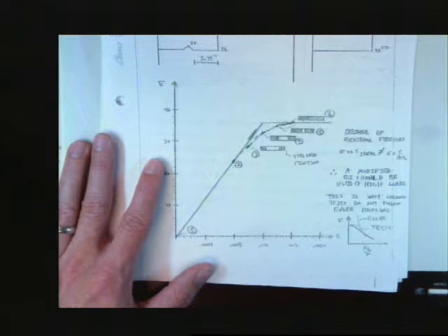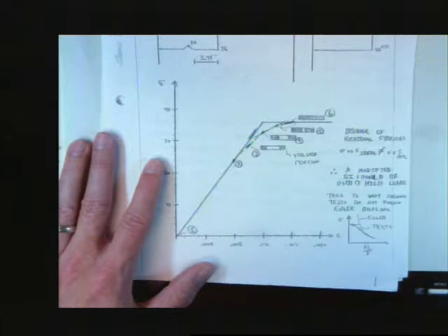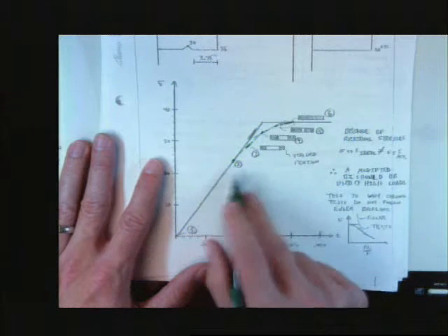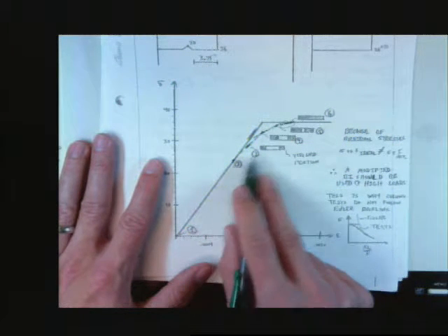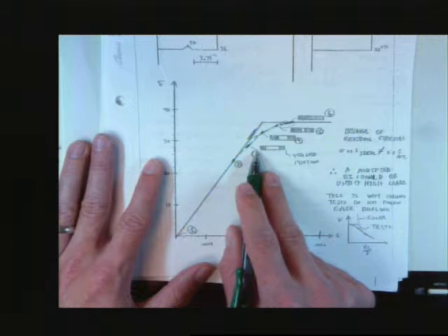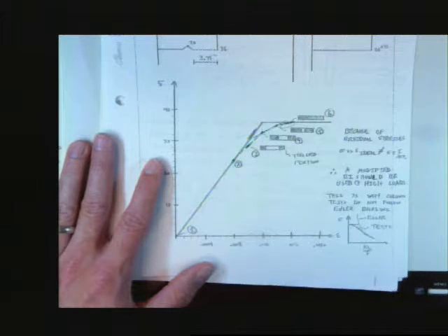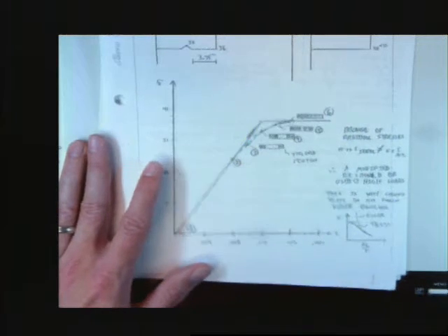That means that initial assumption, that the modulus of the girder and the modulus of the beam or the modulus of all columns are the same, is not right. Because if you get this area above 0.44 Fy, it doesn't apply anymore. You actually have to reduce your modulus.